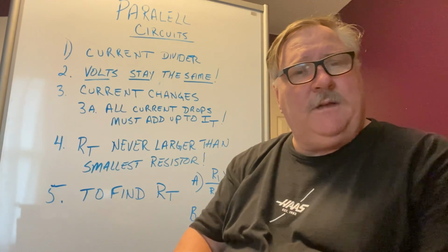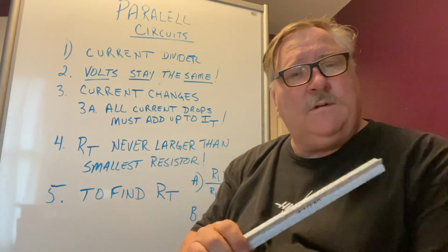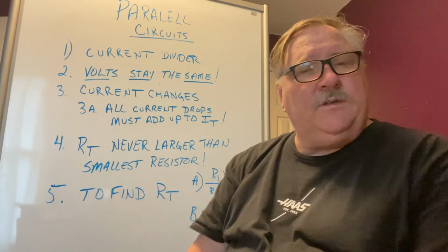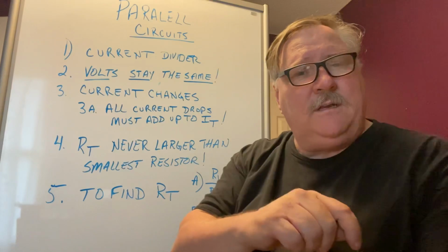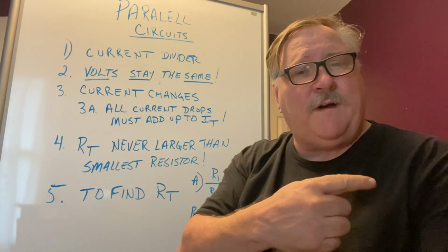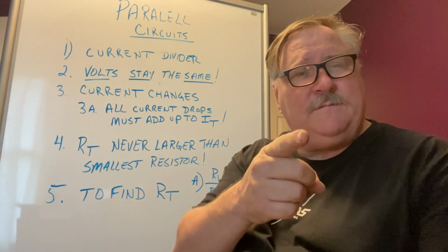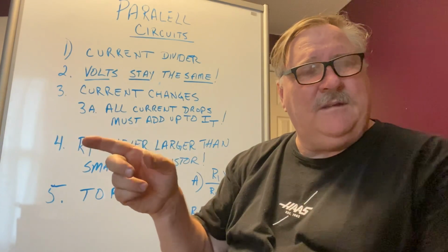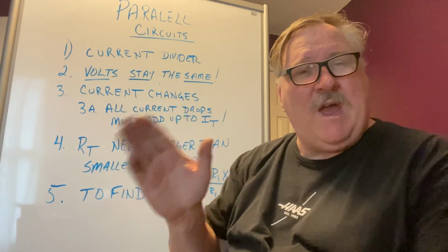So everything that gets plugged into this room right here where I'm at, there are four plugs, one on each of these walls. Everywhere I plug in, I'm getting 120 volts. But if I plug in, maxed out at 15 amps, if I plug in something on this wall, it's 5 amps, something on this wall, it's 5 amps, there's 10 amps gone. And if I plug something in on this one here, now I'm at 15 amps. I'm right on the cusp.